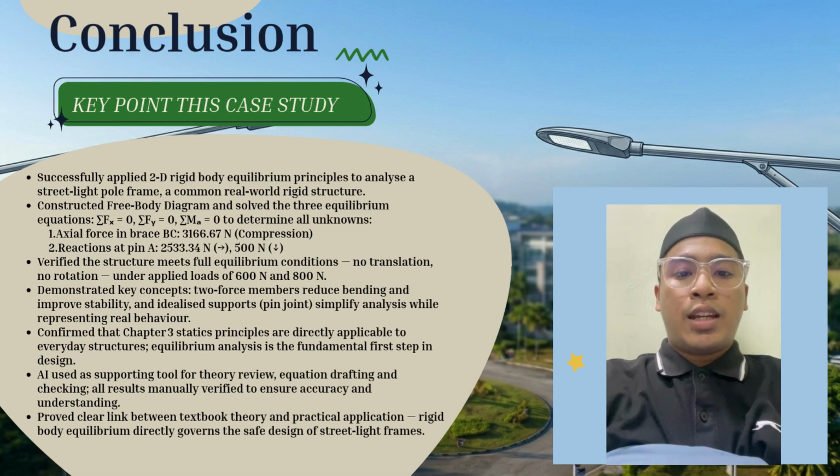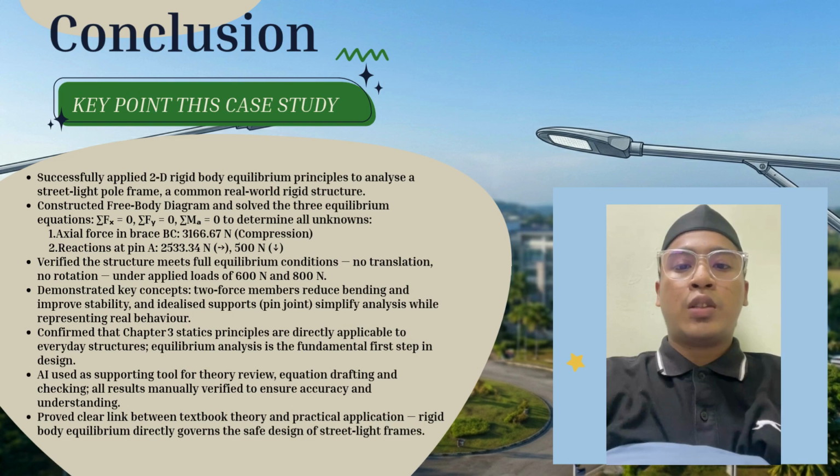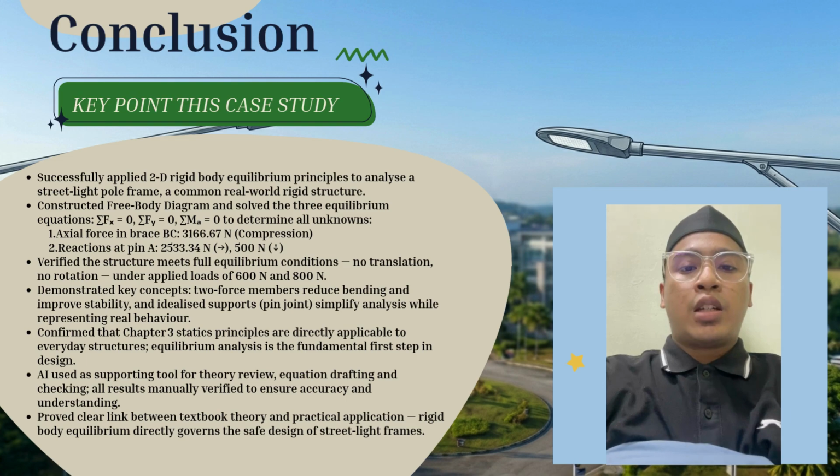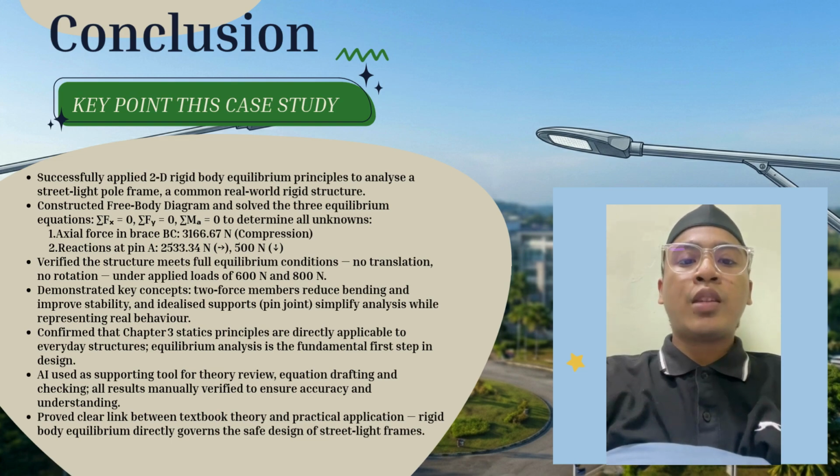First is the axial force in brace BC, total is 3166.67 Newton compression. Number 2, reaction at pin A, 2533.34 Newton positive, 500 Newton negative. We verified the structure meets full equilibrium condition, no translation, no rotation, under applied loads of 600 Newton and 800 Newton.